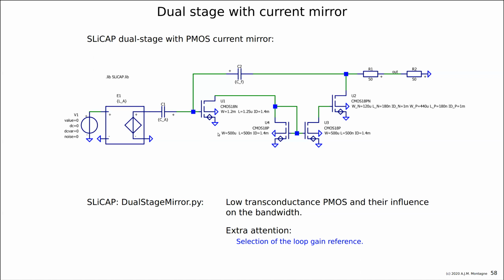So everywhere where you want to select your control source of the stage as reference, you are in a local loop. This will be clear in the asymptotic gain. And you can break the local loop, and that is a nice thing also about SLIDECAP, just by putting the capacitance to 0.